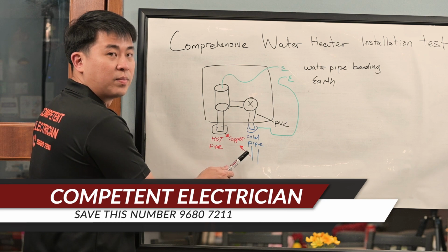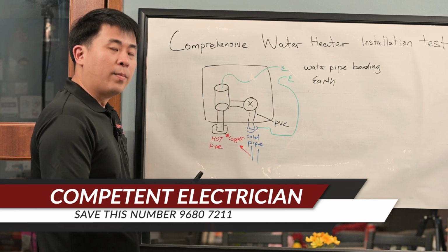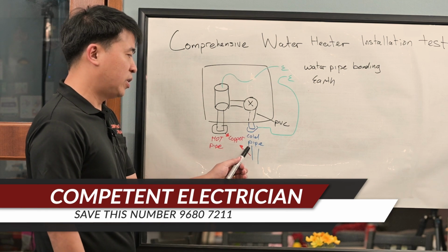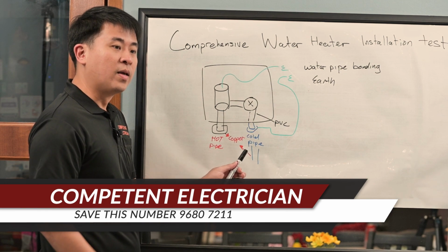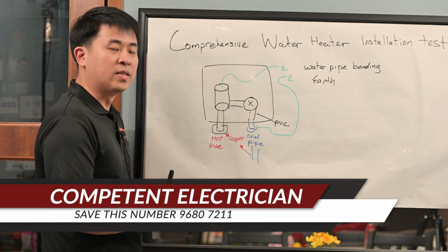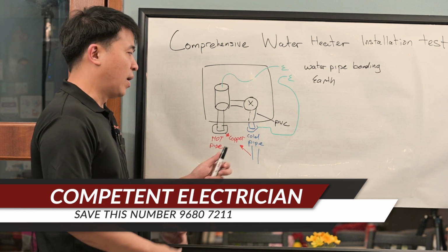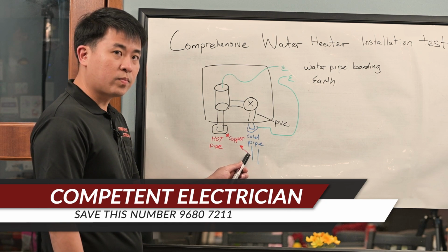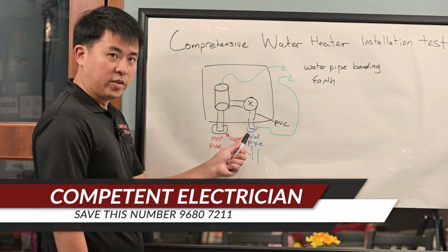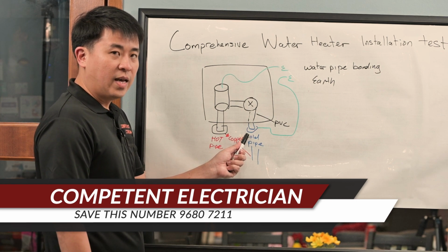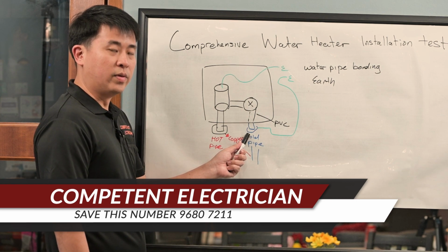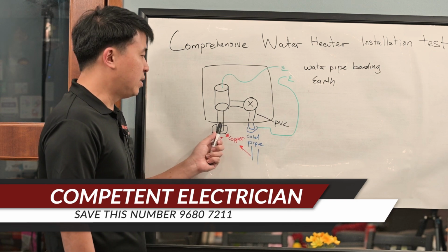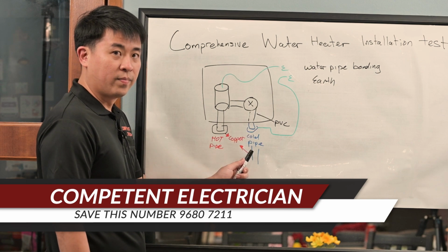Okay, because the main incoming water pipe from the power grid has been grounded. So this pipe is supposed to be grounded, but in between so many buildings and in between your main outlet and the internal of your house, are there any changes, right? So this portion must be checked to see whether there is any difference in the ground resistance, or whether there is any continuity. That means this must have continuity towards the cold pipe.